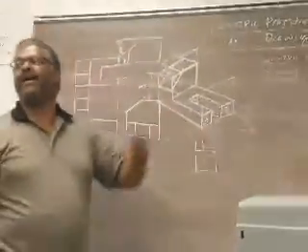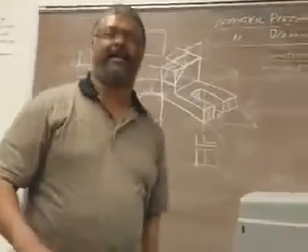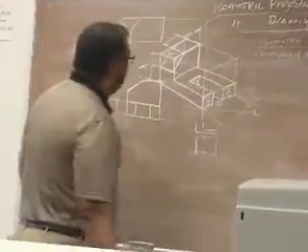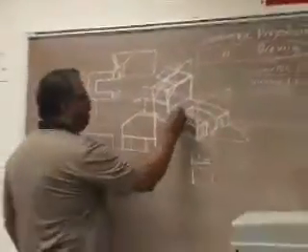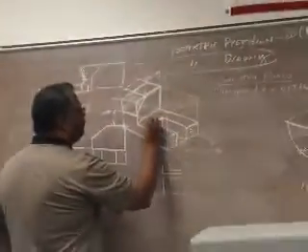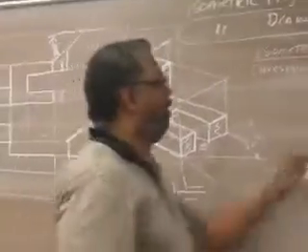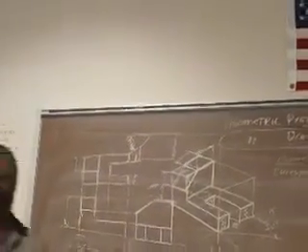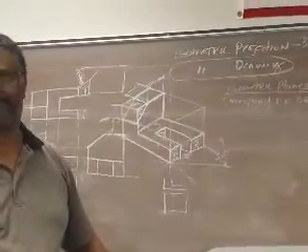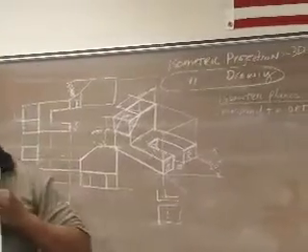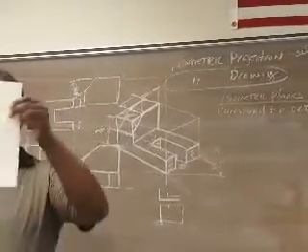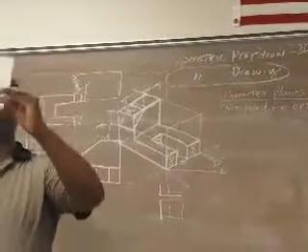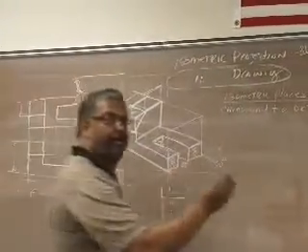Now, if I had a hole in the object, because you do have a hole in that first object, let's say I had a hole sitting here. Well, orthographically, it's going to be round. Okay, so don't make it elliptical. But when you rotate it, it looks elliptical. Just like if you were to draw a circle on a sheet of paper, and it was actually round, and then you change the angle at which you looked at the circle, it would look elliptical.